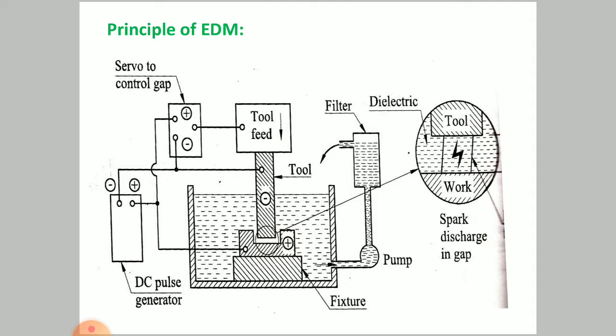That gap will result in the formation of spark, and generally the gap maintained between the workpiece and the tool is usually 0.01 to 0.5 mm, and you can observe it is dipped into a dielectric fluid, right?